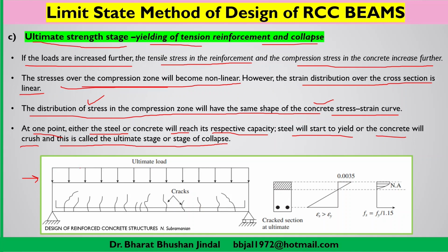And from the top we are applying some load, and when the load is reaching the ultimate stage, the ultimate load, you can see here some cracks are developed, which are inclined cracks from the bottom of the beam, and they are propagating towards the neutral axis. So this will basically be the cracked section at the ultimate stage.